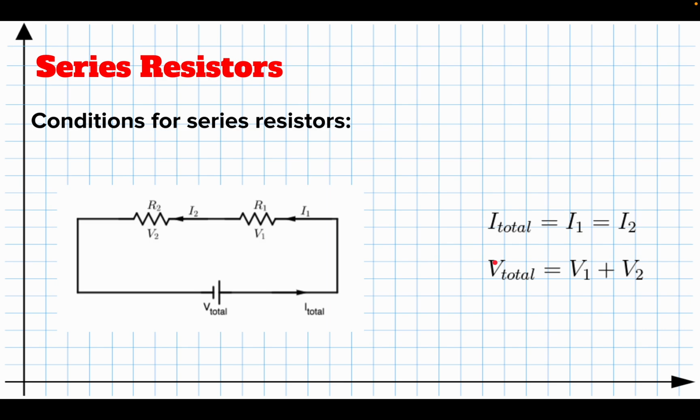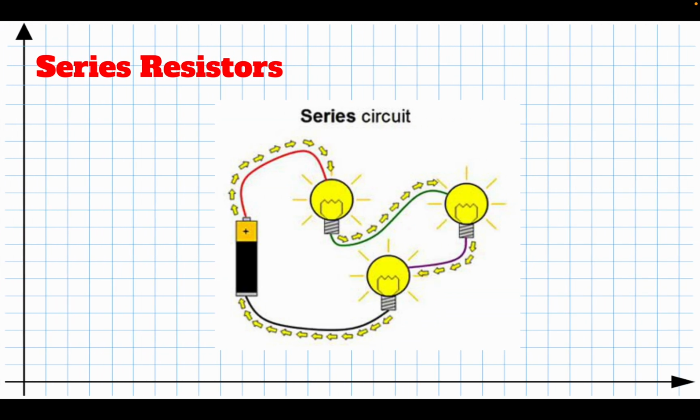So that leads us to the idea that if you want to know the total resistance of the whole circuit, it can be found by taking resistance 1 plus resistance 2. Okay, so this is in your toolbox, and that's also what you found in lab on Tuesday when we did the simulation with the resistors in series.